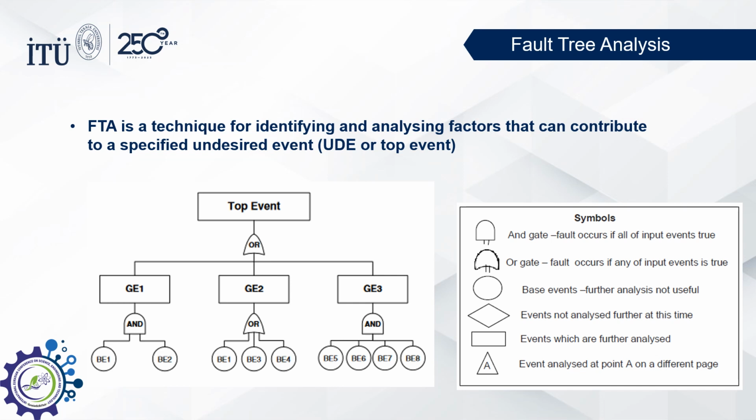A fault tree is a logical diagram that is created by decomposing internal and external root causes. You can see here an example of a fault tree structure. Fault trees have a basic structure. The top event in any fault tree is the failure event. Basic events represent the lowest level of each branch in the fault tree. The top event is usually connected to basic events through gate events. The major task is constructing a fault tree, and it requires the participation of experts from several different disciplines.